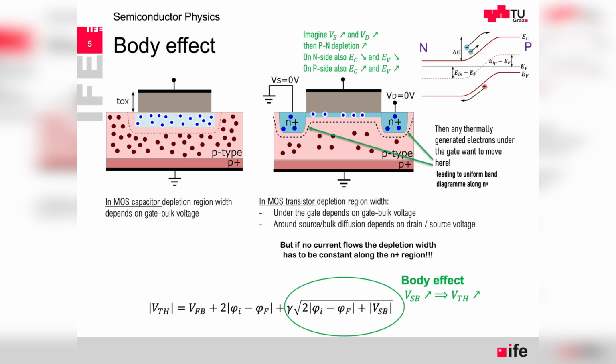The only thing we changed is adding the source and drain terminals. First, we look at the threshold voltage in the second case with respect to the source, and not absolutely judging the bulk-to-gate voltage. So that's the primary difference. But the second thing is why the threshold voltage is changing at all.